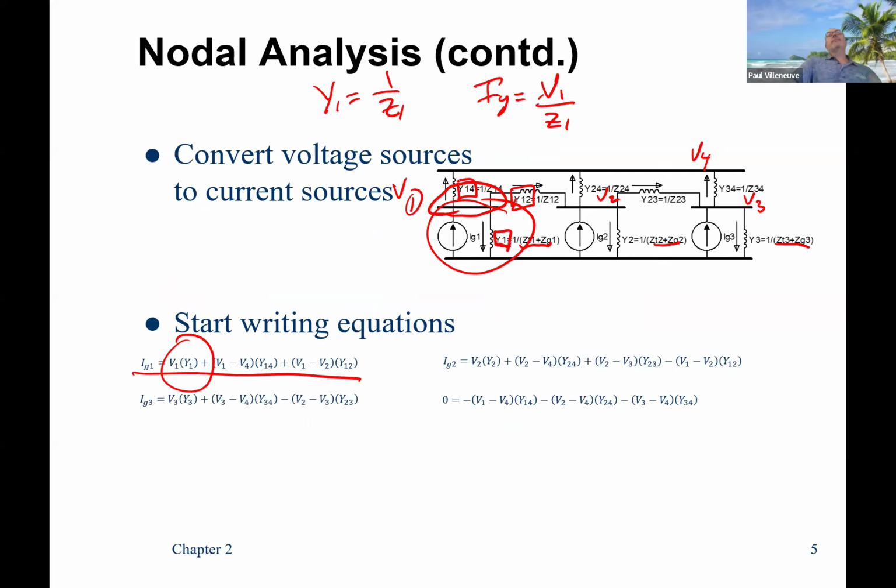You said B1, B2, B3, B4. How about the bus at the bottom, the B5? It is a node, but it's our reference node, right? So everything is referenced to that point. So for the most part, we'll assume that that's 0 volts. If it's not, you just assume it's 0 volts. And let's say it's at 10 kV, all your voltages will float up 10,000 volts higher. So we can't solve for all the node voltages in the system without having at least one reference bus. That's the reason why we don't touch that one.